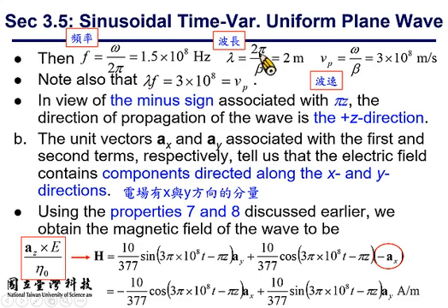So it's 150 megahertz or 1.5 times 10 to the 8th, all right? And the wavelength, lambda, can be found from the phase constant beta. And from the definition, lambda equals 2 pi over beta. And we know from the previous page that beta is what?